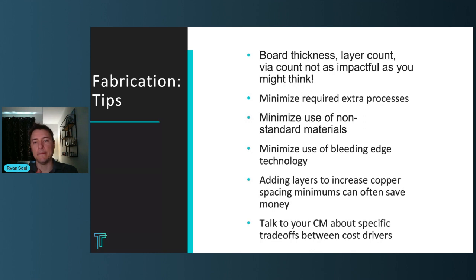So one of the things that is a big misconception that I think a lot of our customers have is that I should try to reduce my layer count. I should try to reduce my number of drills. And to a certain, very linear extent, it is true that layer count and drill count do impact cost.